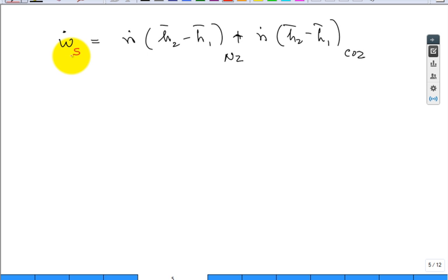So it's reversible, adiabatic. That's how the compressor is behaving, hence it's going to be isentropically compressed. It doesn't change H bar 1, it changes H bar 2, doesn't it? And it doesn't change the molar flow rates. And if you think about it, these were only a function of temperature. It really is, I need to get T2S. Hey, T2 actual was 440.